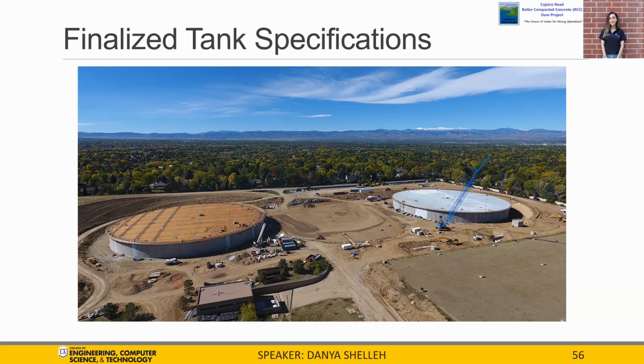Each tank will have the following dimensions: a height of 34 feet, allowing 4 feet of freeboard, a 100-foot diameter, and a 20-foot road to sit between the tanks and allow access for maintenance workers.